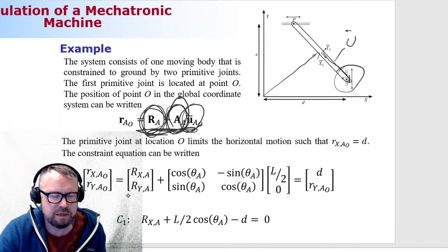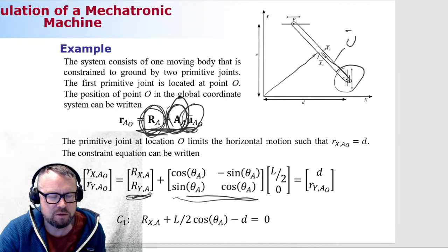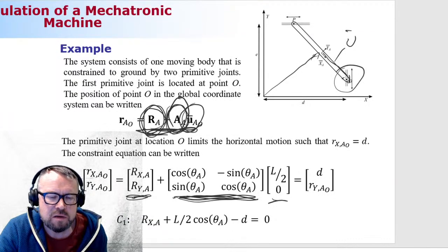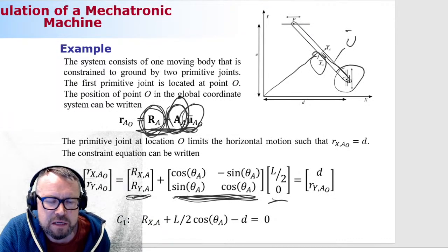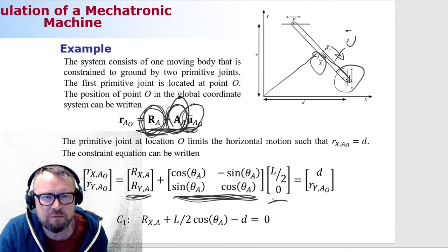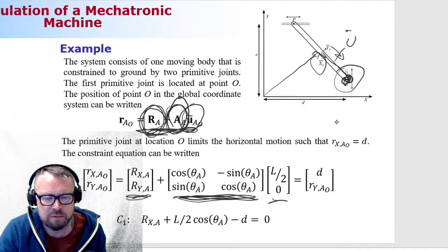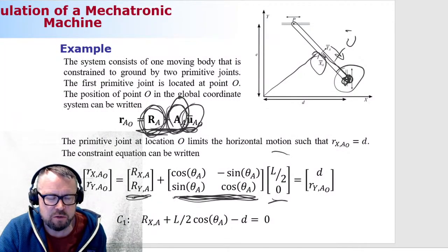And here it is expressed using vectors and matrices. So this is a vector that takes us to the origin of the body reference coordinate system. This is a 2 by 2 rotation matrix. Vector U bar is the only one that is a little difficult, but not so difficult eventually, because if you look at this carefully, the x-axis is pointing downwards. So we need to travel along the x-axis to reach this location. All right, so that's the vector U bar.